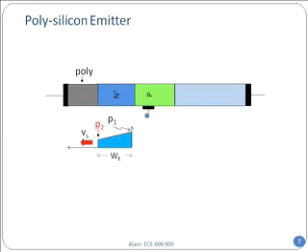So this is how it works. What the polysilicon transistor does is the following. You remember, what we are trying to do is increase gain, but we are trying to increase gain by keeping the collector current the same, but by suppressing the base current. So what I am going to show you is how to suppress the base current, because gain, either you can increase the numerator or you can decrease the denominator. Either way it's fine, so long as you are just looking for gain. And so what we will show you here is how to suppress the base current.